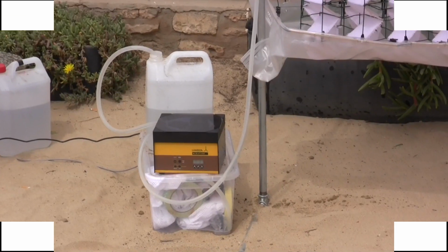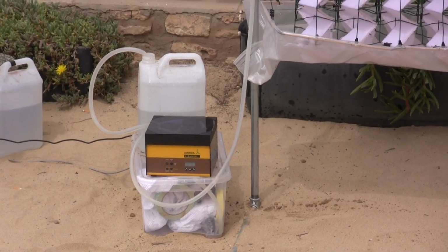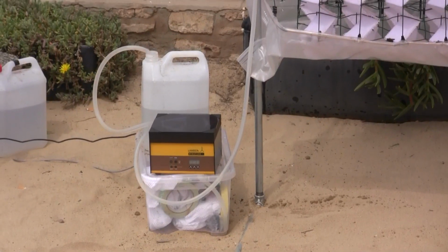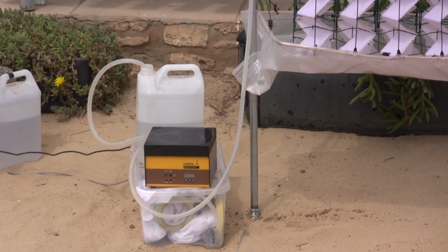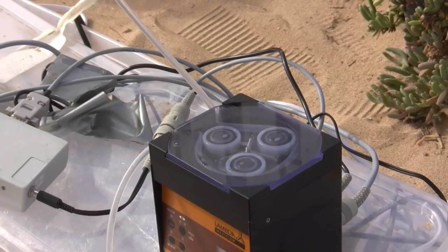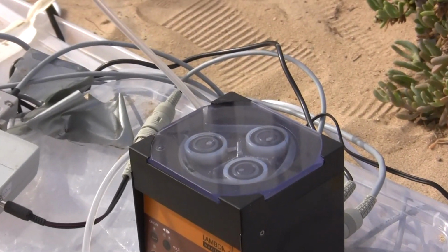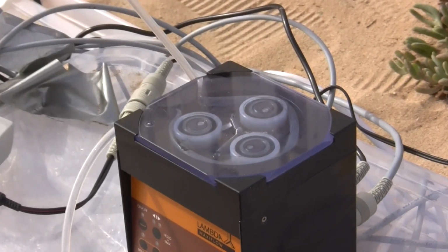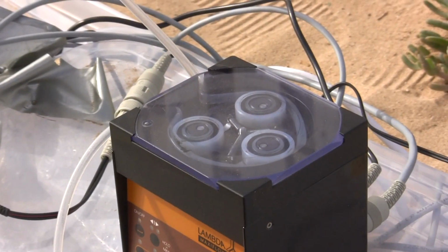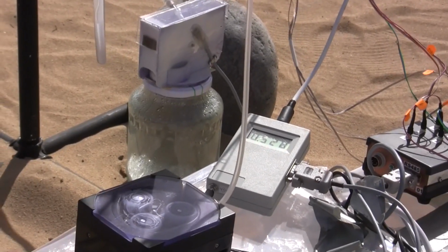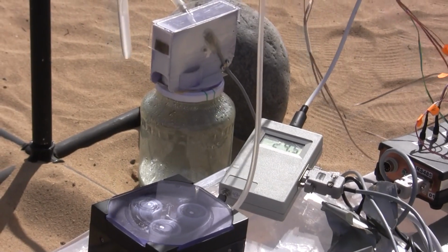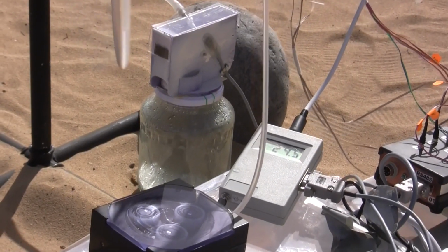Measuring devices were connected to the system for the competition purposes. A peristaltic pump was used to control and measure the flow rate of the concentrated glycerol solution to the water absorption module, and also for pumping of the hydrated glycerol into the water extraction module. The energy source for the liquid desiccant pumping is electrical energy from the local electrical grid, or it could also be supplied from a storage battery connected to a solar photovoltaic array.